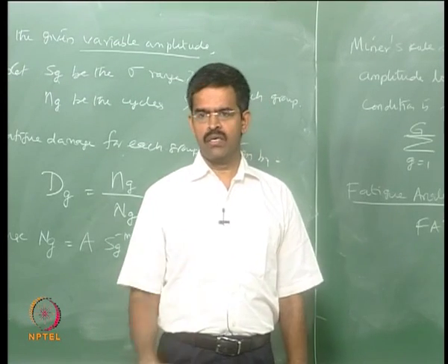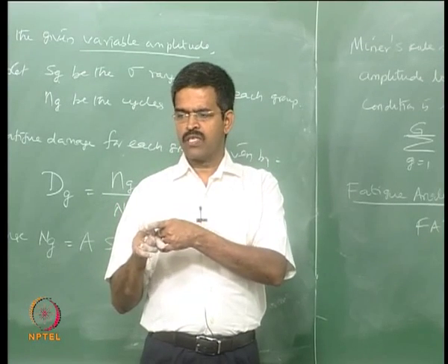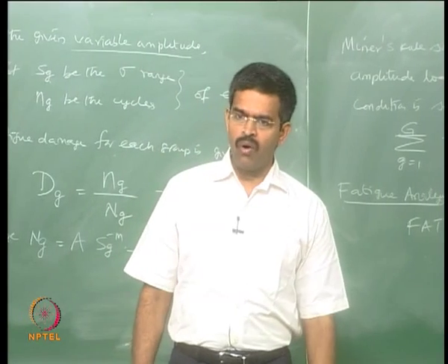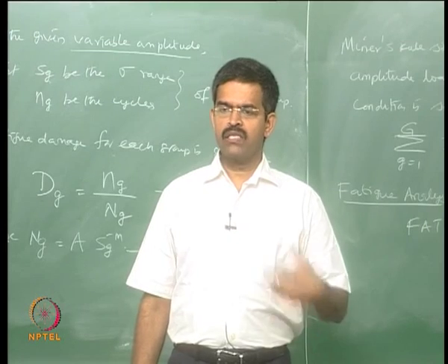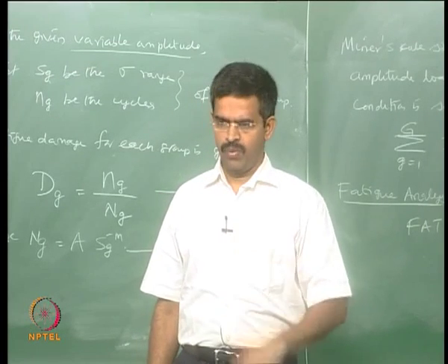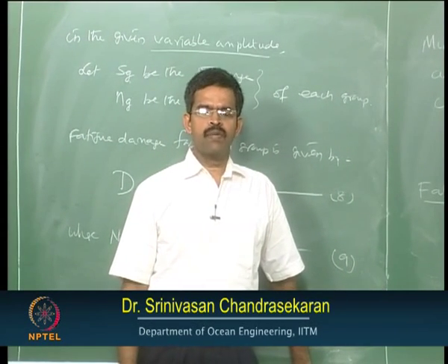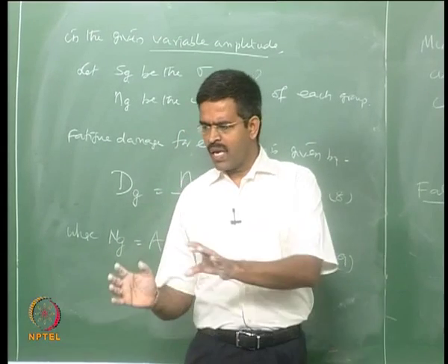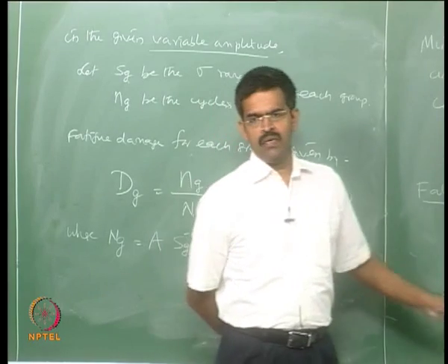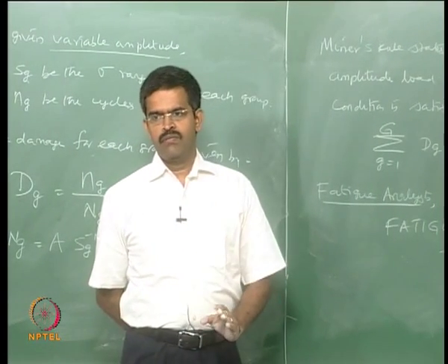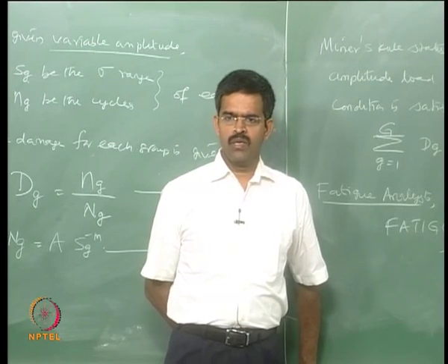If you really want to look at the fatigue estimate for the design prediction of the structure under cyclic loading, one should look at the nonlinear component, the variation of slope components in SN curves, where the SN curve does not remain on the same slope. So, the experiments conducted on the lab scale to estimate SN curves cannot directly map the behavior in reality, but still, to a greater agreement, international codes do recommend fatigue life estimates based on SN curves. Okay, thank you.